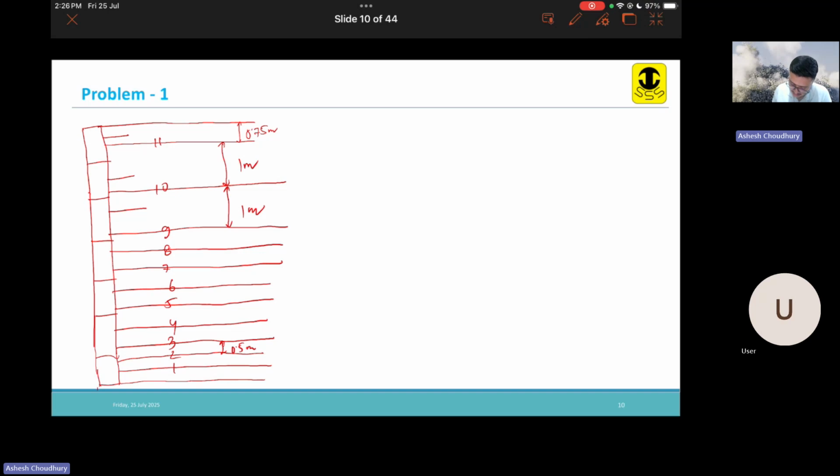But when you are putting 1 meter spacing, there might be an extra disturbing moment that develops. This might not be stable. So that's why we introduce these small short strips, just to hold these blocks properly in position.